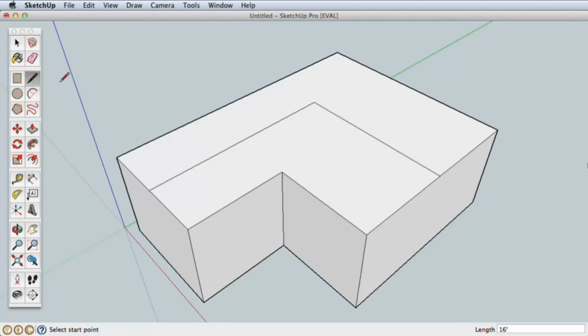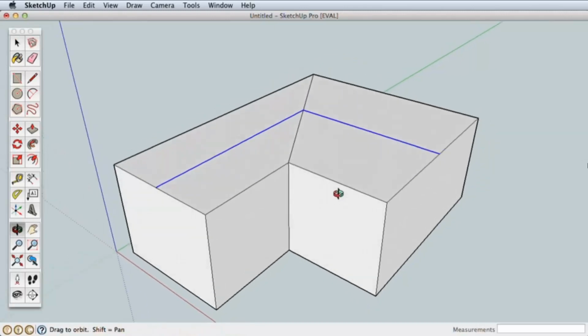Now that we have both ridges in place, simply draw the lines where the roof will fold when we move the ridge lines. Use the select arrow and click on one of the ridges, then hold the Shift key and watch the icon. There is now a plus minus that indicates you can add to or subtract from your current selection. This allows you to select other entities and deselect them as well while holding Shift. Add the other ridgeline to your selection, making sure only these two edges are selected.